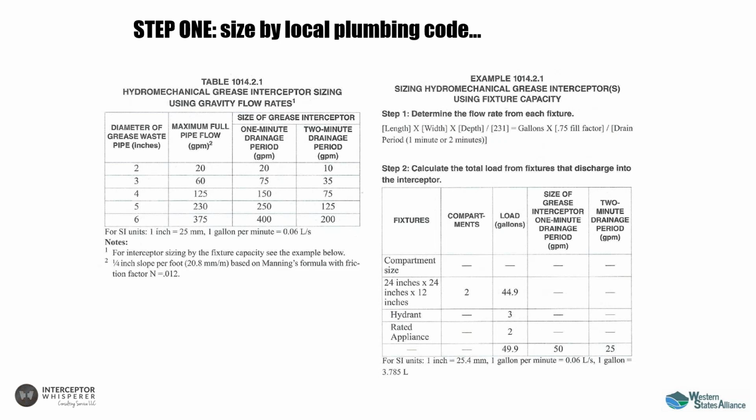And the reason for that is that gravity drainage systems require air to function properly. Without air, we get lots of water hammer and slugs going in there that are very damaging to the system. And so we want air in those systems for them to function properly. And that means that they're designed at peak flow rate to be not more than 50% full. We reserve 50% for air. That's what drainage fixture units are intended to do.